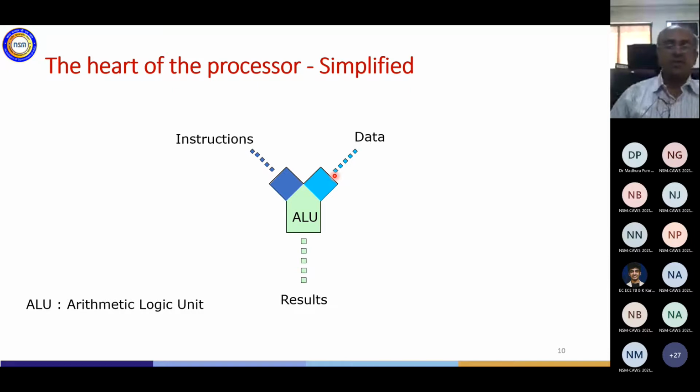So when you say an instruction is executed, it performs certain operations. These operations involve the ALU. Some of the instructions may not involve the ALU, like jump. A jump instruction only changes the flow of the program, or a conditional branch like jump on no carry. Such instructions don't use the ALU, but they will use some other unit inside the CPU. We'll see more about that later. Like in this case, the two operands are 2 and 2, and the opcode is plus, which is shown here as ADD, and you get the result. So that's how it works.